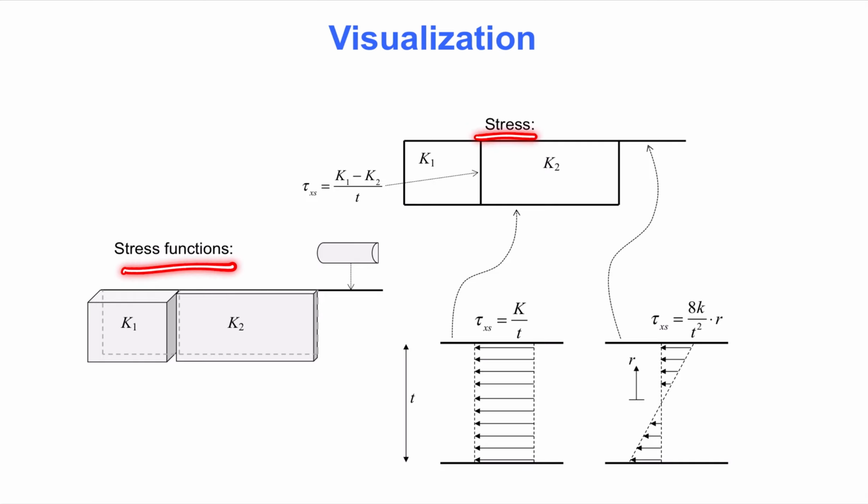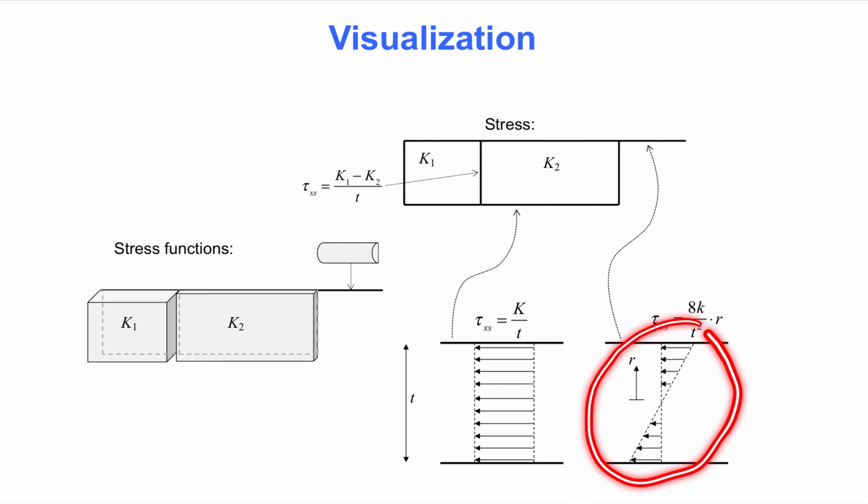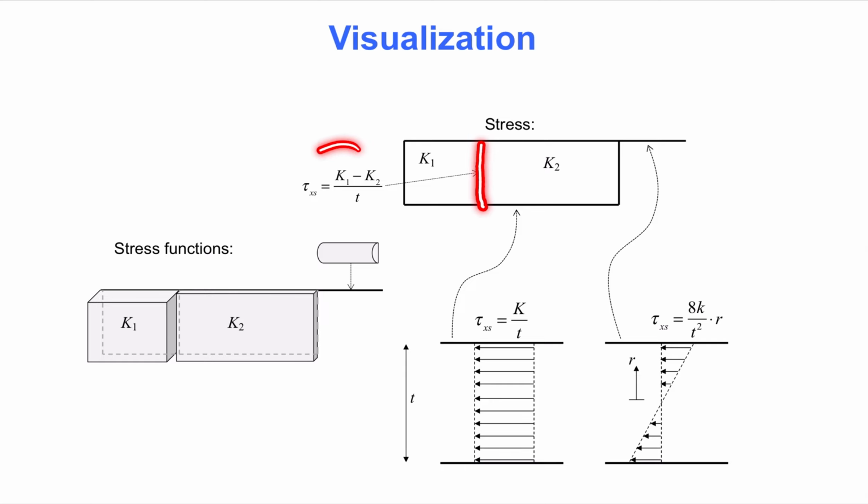Notice that the stress functions in the two cells of this cross-section have different constant, k. Also, notice that the stress function for the free flange is the half cylinder that we saw previously in this video for an open cross-section. The result is the stress distributions shown at the bottom of this slide. Notice the linearly varying stress and the constant stress across the thickness of different cross-section parts, which we have seen earlier. Also, notice the subtraction of shear flows from adjacent cells in the wall that separates them.